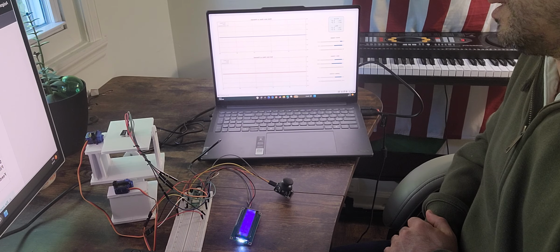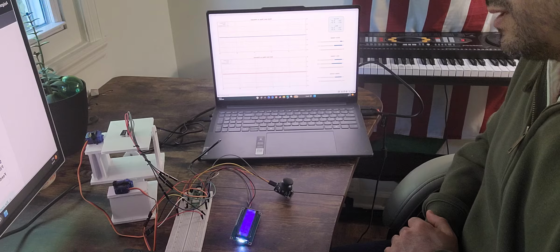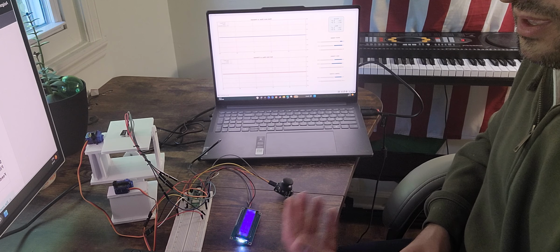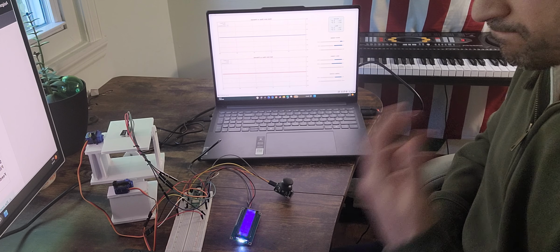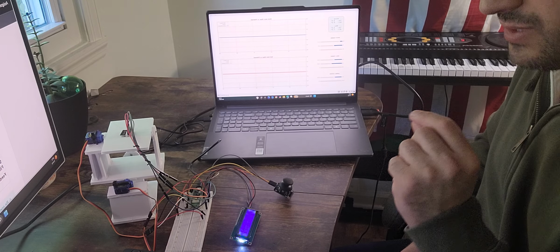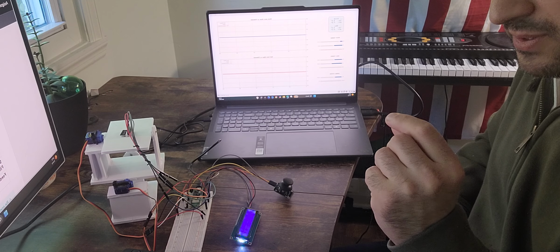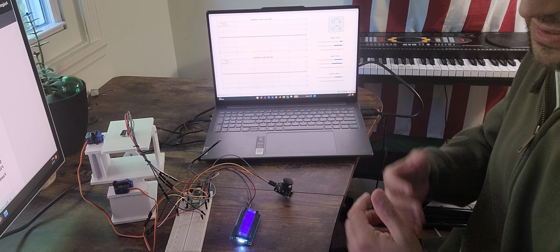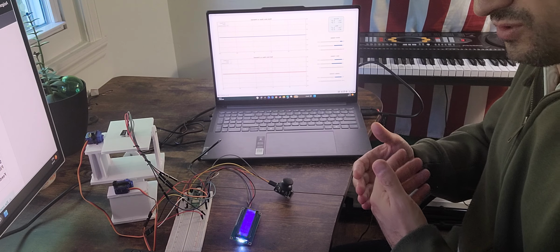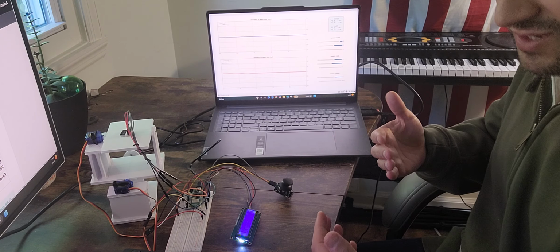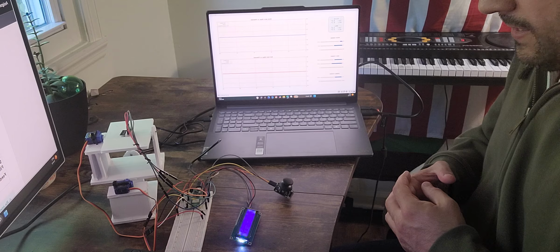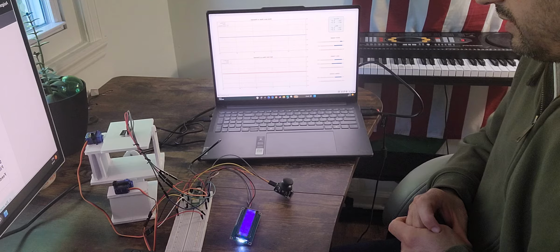So because of it, I have to use incremental PID, which is basically a derivative of the standard PID, and just calculate the adjustment step and keep adding that to the previous one, which is like integration. So you take the derivative first and then reintegrate it, and basically get the same thing, more or less.